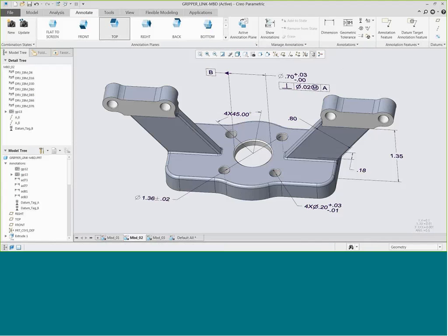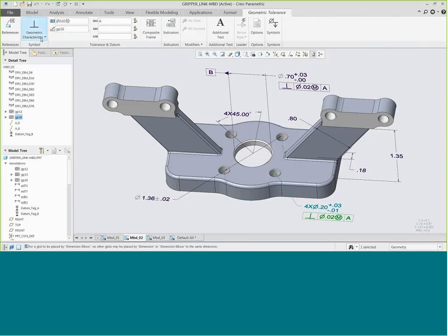And what's important here is if we go and then use this part in manufacturing or in CMM, then it will recognize that this tolerance isn't just on the 1 hole, it's on all 4 because it is semantically placed, not just graphically placed.